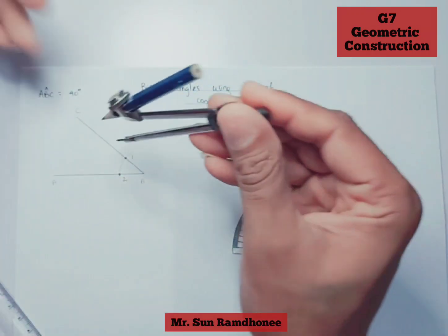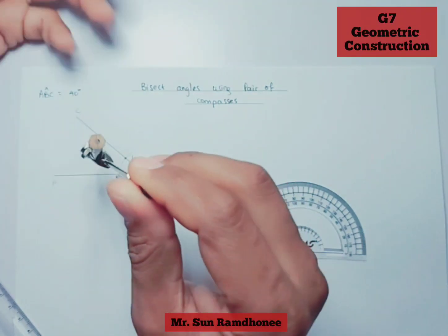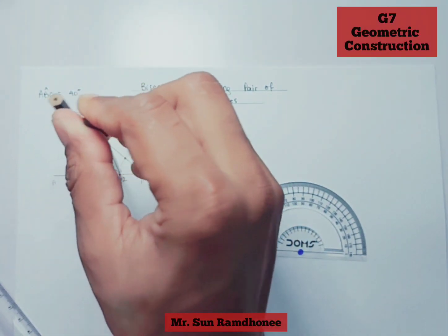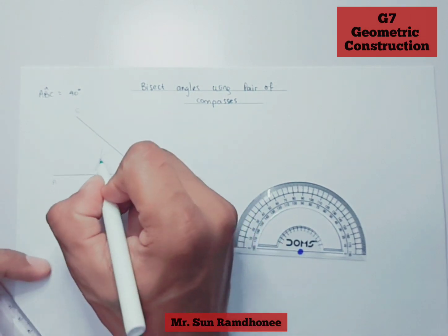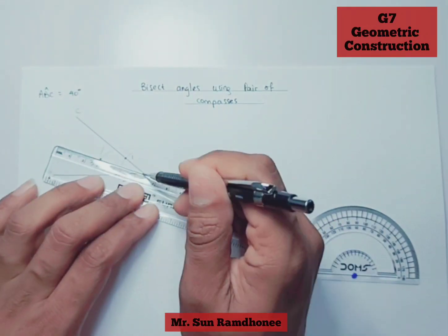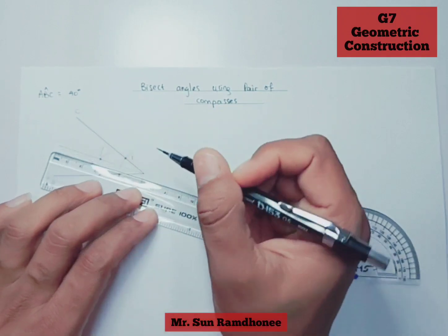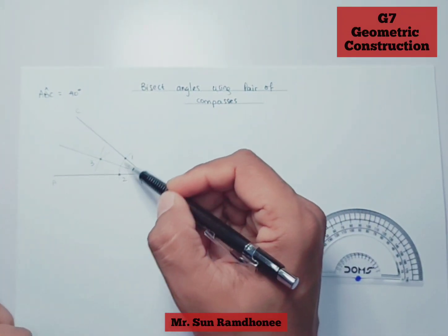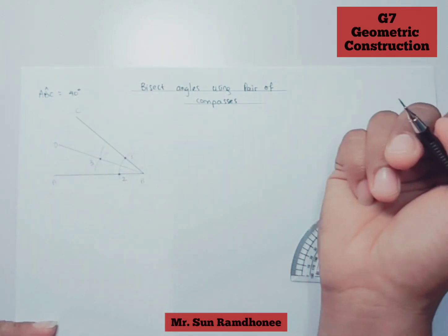Without changing this dimension, I can draw an arc here and then another arc here. When I have drawn these two arcs, I'll obtain point 3. Once I have drawn point 3, I'm going to draw this line which is in the middle, which separates these two angles into two equal parts. We can also call it line AD.